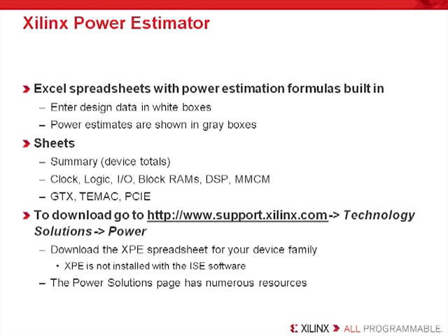Now, this slide is trying to highlight some of the benefits of the dedicated hardware resources that exist. The most useful is the DSP slice and the block RAM resources. Besides using less power and saving FPGA resources, that is, the primary resources, LUTs and registers, using the dedicated hardware makes it easier to estimate your timing, and that's because the architecture delays of the dedicated hardware are known or fixed before place and route.